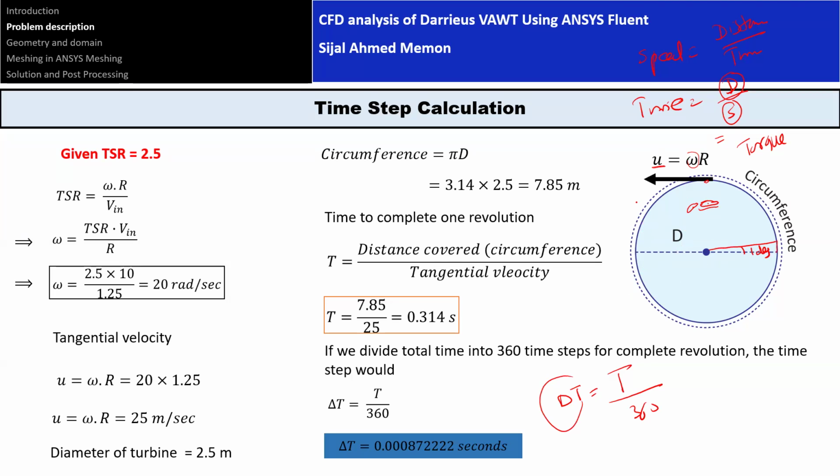So the CFD of the winglet will be the same. A winglet will be affecting the lift and drag, and also it will be affecting the wingtip vortices. Okay. So the procedure is the same, the geometry making is the same. You will define the boundary conditions in exactly the same way. You define the domain in exactly the same way. But definitely now you also have the winglet on the wingtip, and here you will be defining mesh on that part. Okay.